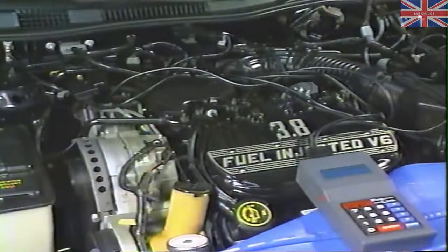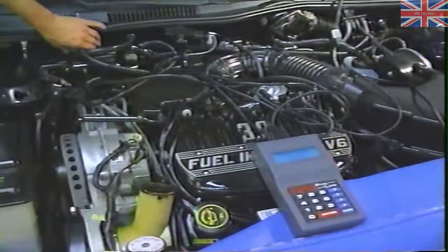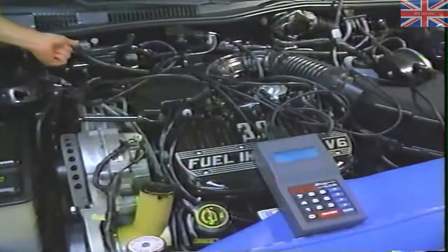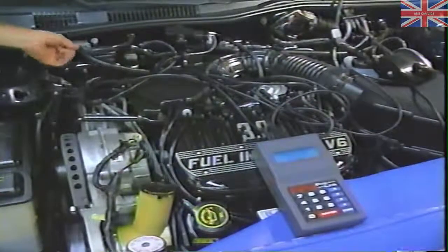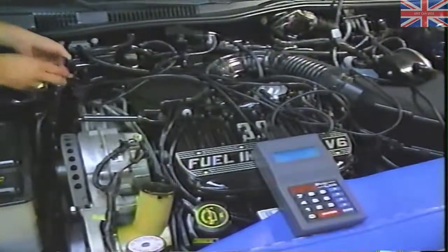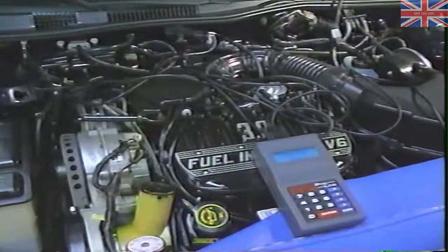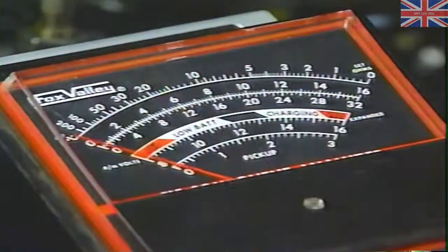Approximately 2 minutes after the passcode 11 has been displayed for on-demand codes, the system will enter continuous monitor mode until you deactivate the system by turning off the engine. Carefully go through each wiring harness, sensor, and solenoid assembly, tapping, wiggling, twisting wires, etc., until you have initiated a code. We have a continuous self-test code 18 again.